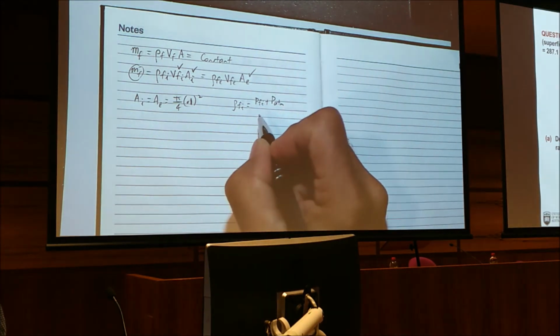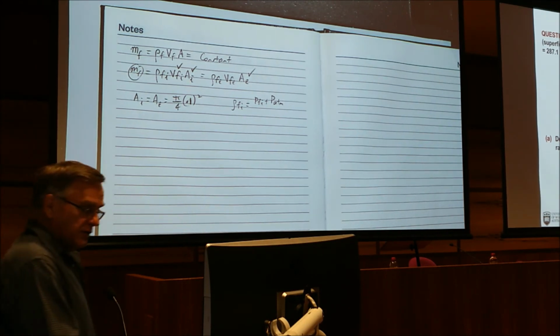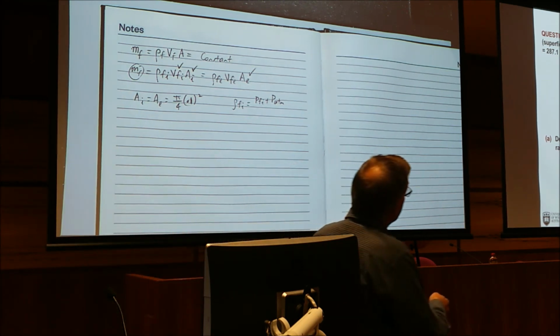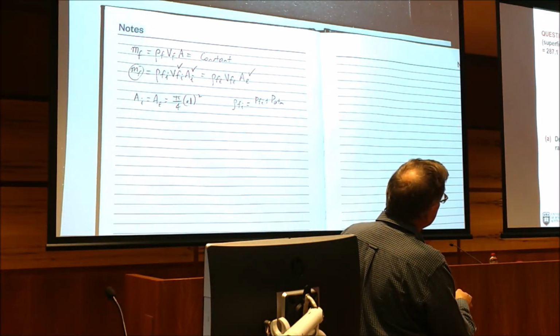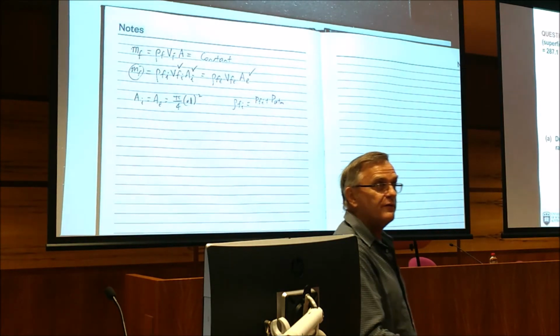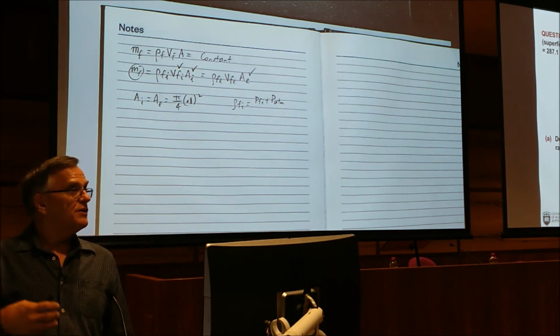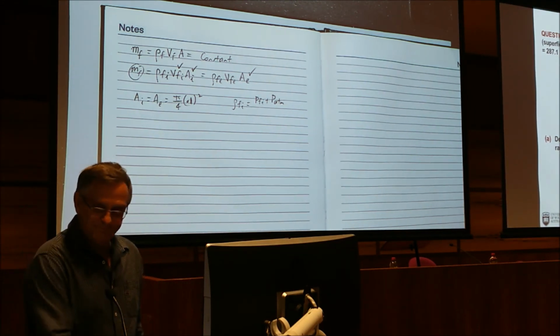That's the absolute pressure at the inlet. What we're doing really is putting a pressure gauge there, and that's going to read 50 kPa gauge, and we've got to convert it to absolute units. So we've got to add atmosphere to it, 101.